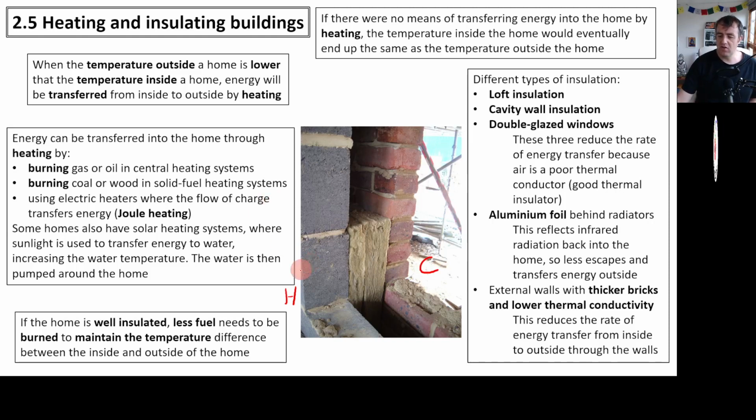So energy is going to be transferred from the hot side to the cold side. And we know that we can reduce that rate of energy transfer by increasing the distance. It's a nice big thick wall, so that works. By reducing the conductivity, well, we've trapped air in the insulation because there's air trapped in the fibres, so that's a big tick. And by reducing the temperature change across that gap. So how do we reduce the temperature change? Well, these are the ways we can do it.